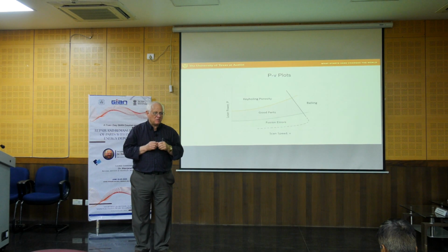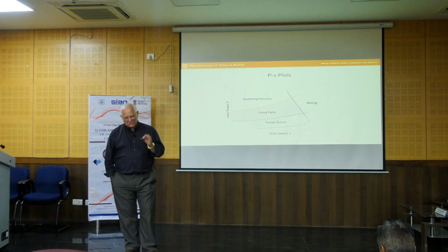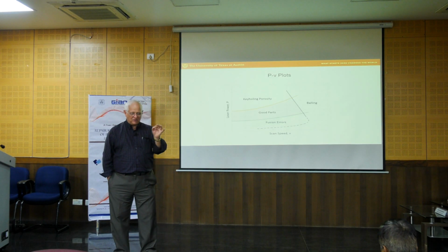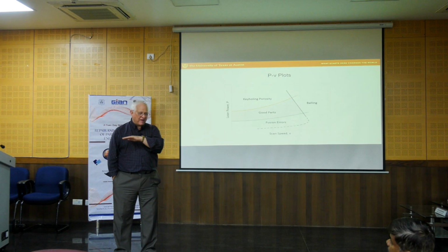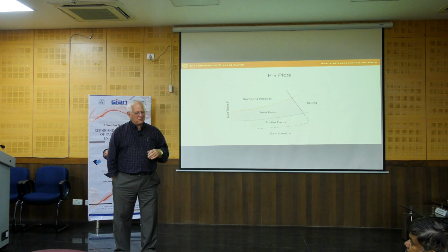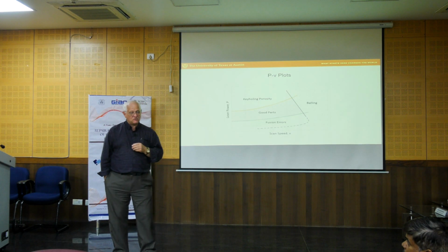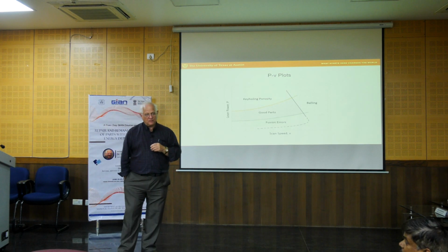It would be almost impossible to do in powder bed. People have worked on this with powder bed, where you take a little nozzle, you have sort of a matrix material that's the powder bed, then you come back over and deposit material locally, but it's just not very well suited. It's so much easier with DED to do functionally graded materials.